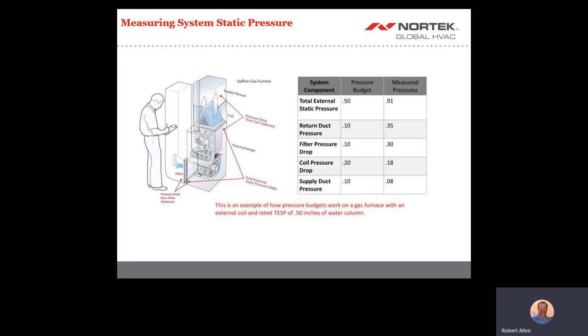And finally, the opportunities out there for you as contractors. Measuring static pressure unlocks the door to the system as a whole and allows you to see the system in an entirely new light, where airflow now becomes visible. It allows your company the ability to prescribe and fix ductwork issues, providing comfort and efficiency to your customers. Only by getting the ductwork operating issues fixed correctly can you assure the system as a whole is operating properly.